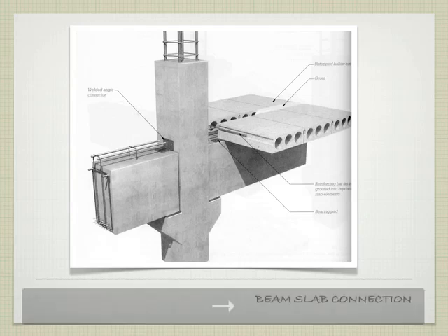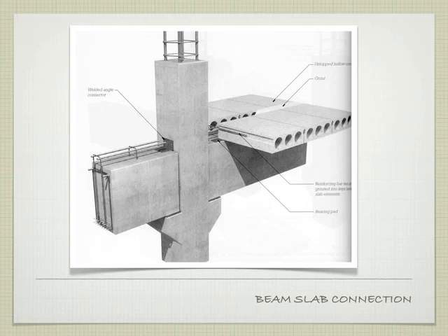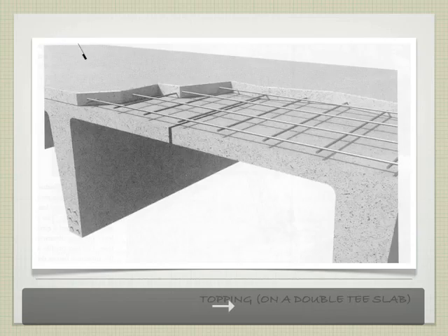Okay? If we extend this even further, we put our hollow core slabs in the same situation. We have steel running along in between these two slabs. We also have this gap on top of the beam, which we saw earlier in the photographs, that has the little loops embedded in the beams. All of this gets topped together, or in this particular case, they're just putting grout in between and leaving this as an untopped hollow core slab. I would feel better if it was a topped hollow core slab, but depending on the engineer, they're going to specify different things.